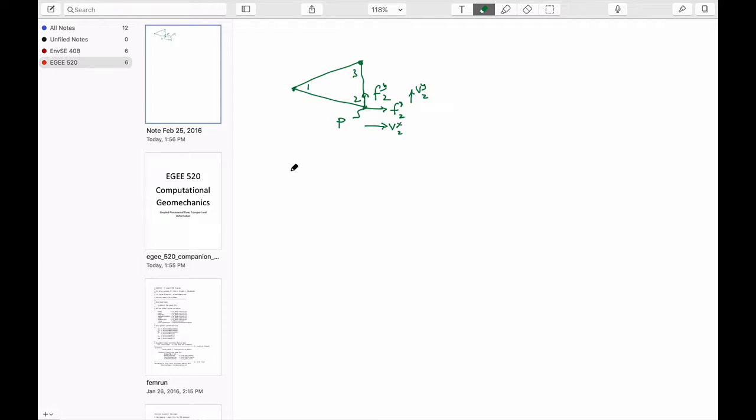When we write the equations that describe the system, because we write them on a node-by-node basis, we would like to write our variables as our matrix. So three degrees of freedom here, three here, and three here. So it's going to be a 9 by 9 matrix. I won't write out that full matrix, but I'll make a stab at what size it would be.